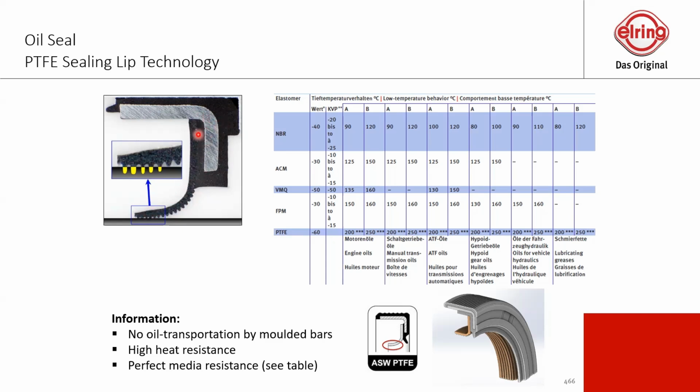It's glued here next to our elastomer material and comes in a defined shape. As you see, we have more contact points in comparison with our classical oil seal, here for example 5. Based on the design of this oil seal, we have more contact possibilities.